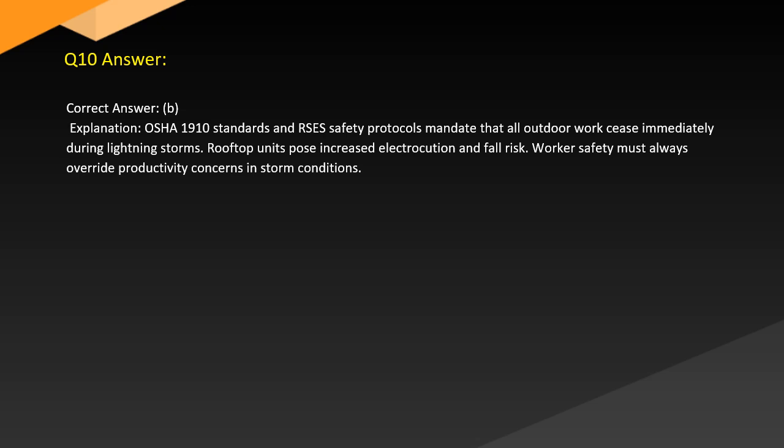Answer. Correct answer: B. Explanation. OSHA 1910 standards and RSES safety protocols mandate that all outdoor work cease immediately during lightning storms. Rooftop units pose increased electrocution and fall risk. Worker safety must always override productivity concerns in storm conditions.